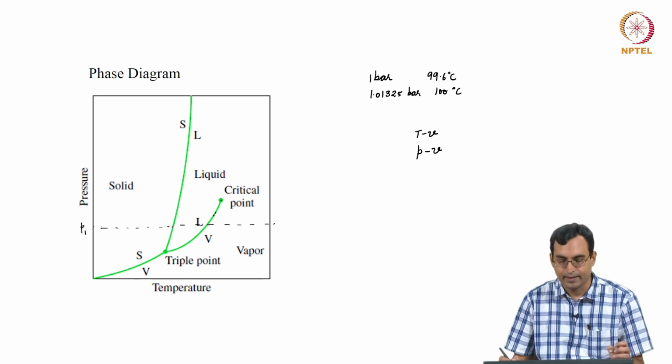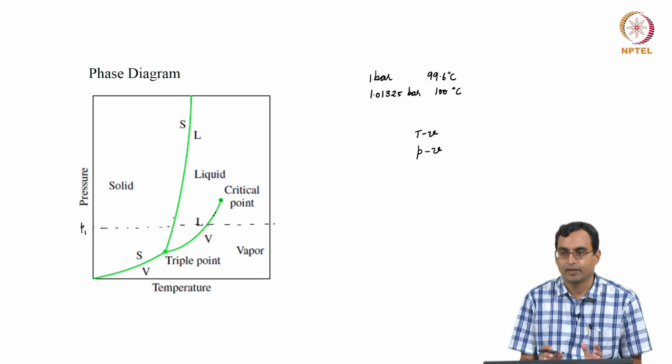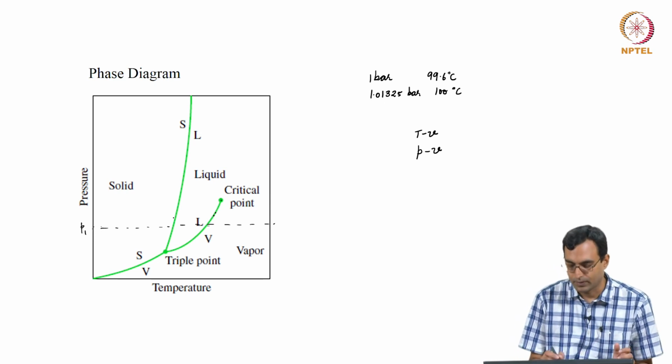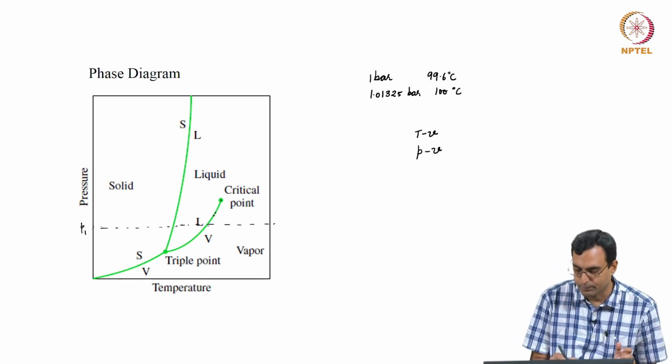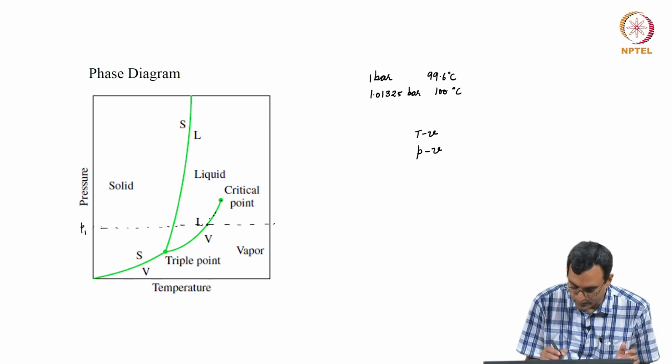After that the temperature starts to increase. So, if I am giving heat up to this point, the temperature increases at constant pressure because I am doing this process at constant pressure. Once I reach here, the temperature remains fixed and conversion happens from solid to liquid, and once complete conversion has happened, the temperature once again starts to increase and I get liquid whose temperature is higher and higher. This happens until I reach this point over here.